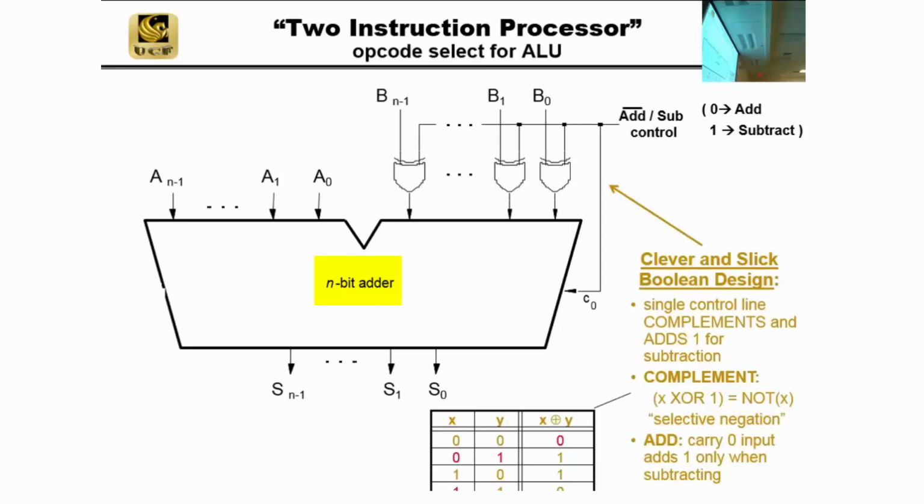It turns out what we have is our first ALU design. It's actually a very simple processor with 2 instructions. One instruction is add and the other is subtract. Go back to module 6. Remember, instructions were encoded as bits. We had fields for op and func. Here we have a processor that has a single bit, either add or subtract, and this is the guts of the processor. So we can take in A and B.